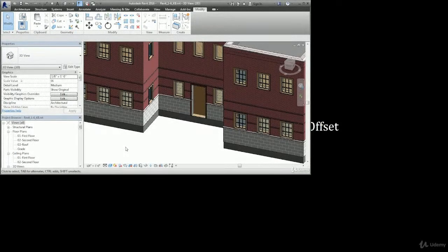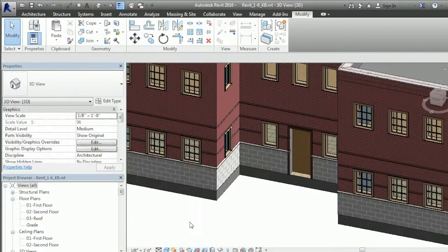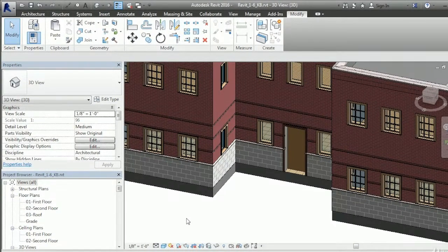We're now going to take a closer look at families, family libraries, and loading families. All elements in Revit architecture belong to families. Each family may have multiple types predefined, and new types may be created by duplicating existing types. When you start a new project, the families which are initially available for use will be determined by the template used to start the project.